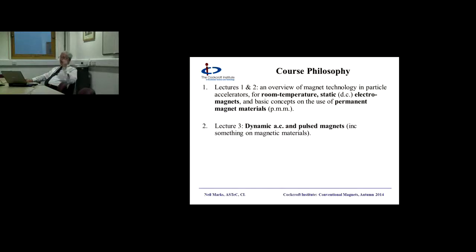So the third lecture is going to be on dynamic and AC magnets, which is something of a Cinderella subject, but of course if you think about it, any circular accelerator, any circular machine that is accelerating is going to have a variable magnetic field, so therefore it is a dynamic situation, and this is often not covered in lectures.